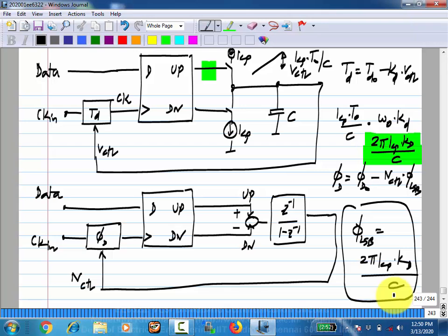No, why 127? I'm saying, what did we compute phi LSB to be? 2 pi by 100, right? So when should it wrap around? Yeah, it should go up from 0 to 99 and then wrap around. Basically, you go all the way to the most delayed one and then wrap around. So this should wrap around after 1 cycle.